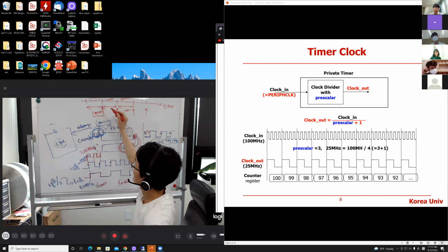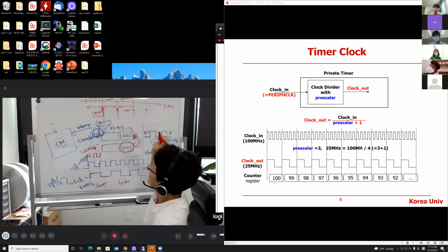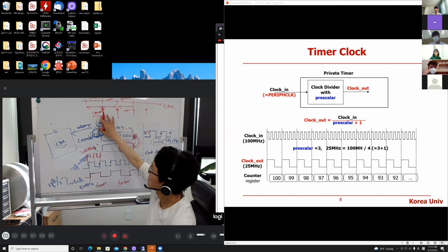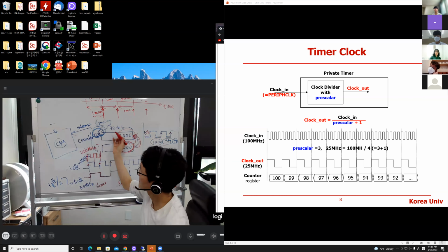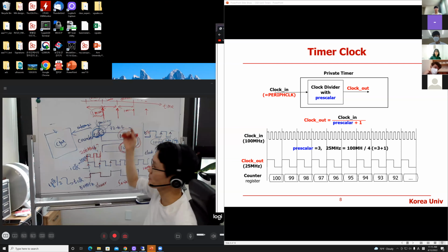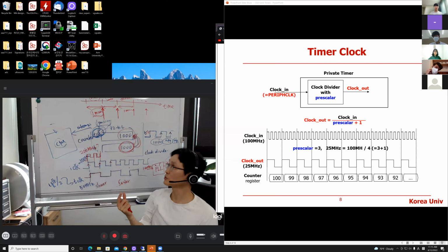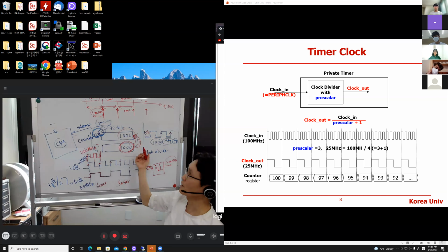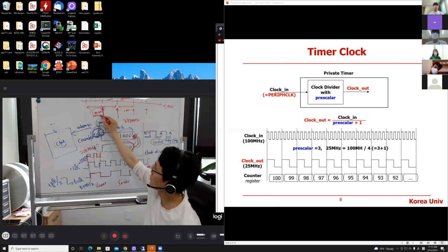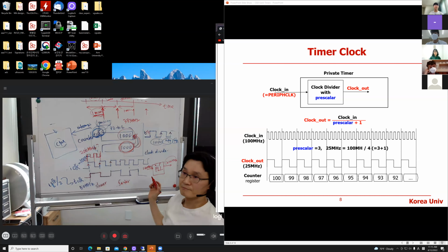That time indication is coming from the timer. The timer is measuring this 1 millisecond, then notifies that event to the CPU. So 1 millisecond is very coarse grain, right? So you don't want to use a very fast clock, right? The 333 megahertz. The goal is to measure 1 millisecond, so you don't need that fast clock frequency.